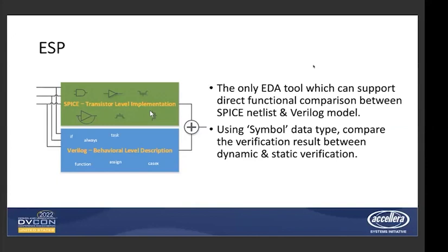By using their own data type symbol, ESP compares the static and dynamic simulation results. However, not only is there a limitation of supported IPs, ESP supports only synchronous design, but it supports multi-cycle operation. So we cannot use various asynchronous designs for ESP simulation.